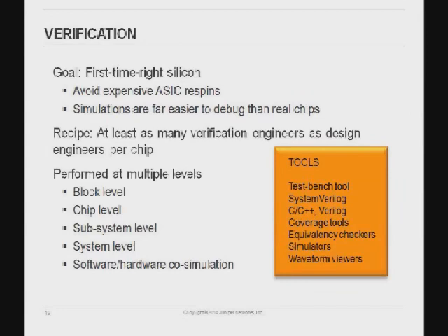The tools we use include C, C++, and SystemVerilog, and people use Verilog as well. We use coverage tools to make sure that we cover every line of code. And then we use equivalence checkers to check between the gates, the machine languages, versus our RTL.